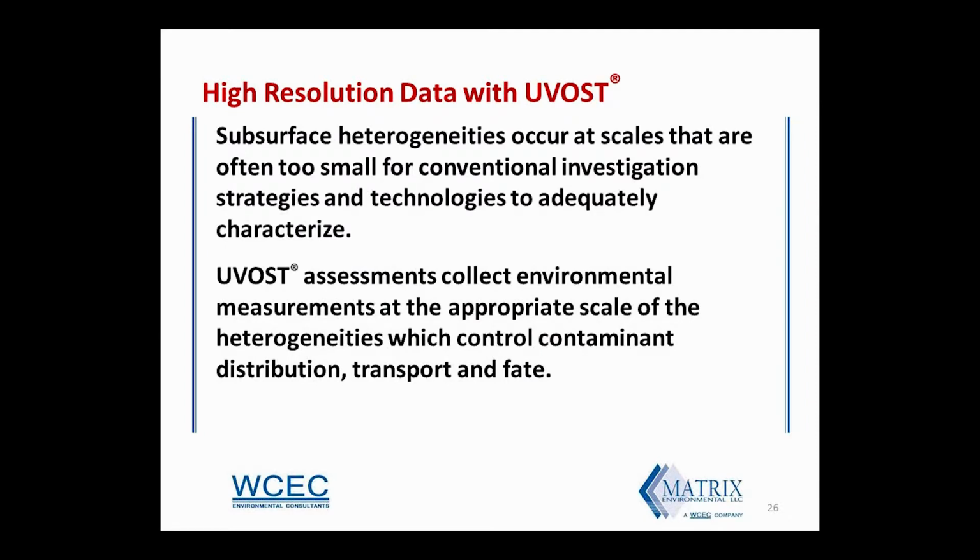And we all know that real-world sites are never like the fish tanks filled with lab sand that the experiments are conducted in. The small-scale subsurface heterogeneities that can go undetected using conventional investigation strategies are really quite often very complex, and they can cause abrupt changes in the LNAPL migration and distribution over very short distances. The UVOST's gridded sampling approach and the density of UVOST data collected vertically appropriately characterize the heterogeneities that control contaminant distribution, transport, and fate.